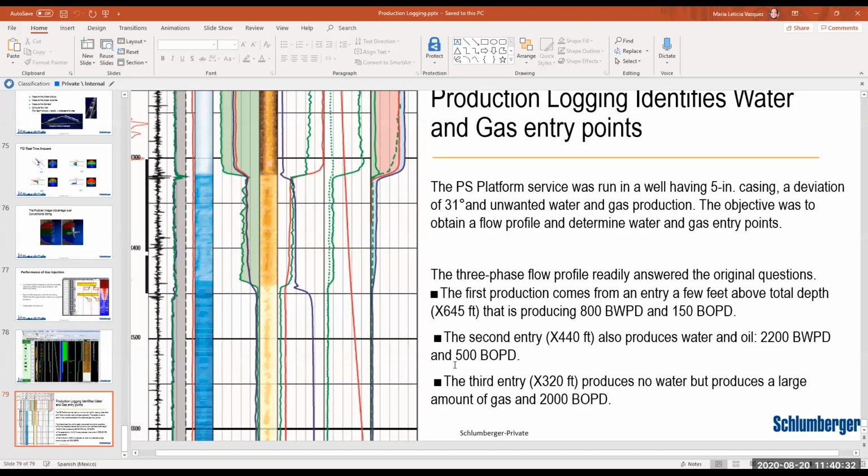Someone says, if velocity is an output and its measurement depends on the Reynolds number, which has velocity as an input, then how is the parameter an output and an input at the same time? Okay, so for the Reynolds number, what we have as an input is the velocity. The velocity will be an output from the calibration of the spinner. What we need to derive the average velocity is what we call the velocity profile correction factor. So how do we derive the velocity profile correction factor?